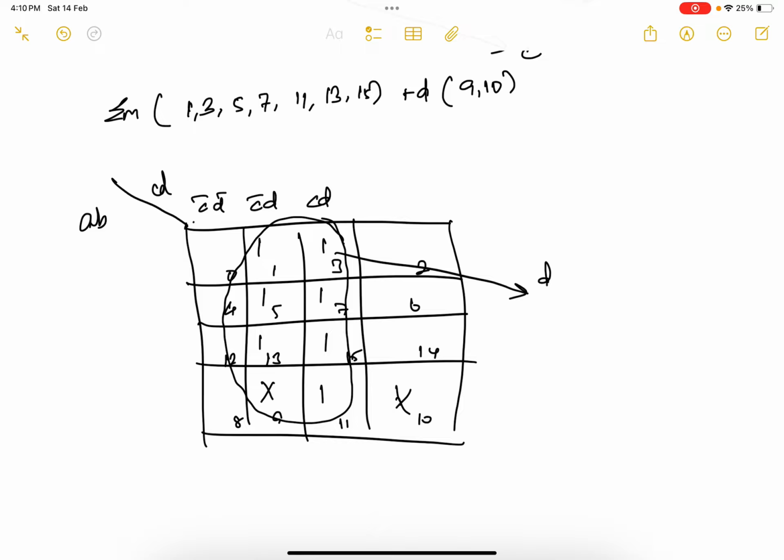But in this case, if I added one more 14, what will you get? You will get a structure like this. So here if you see, I can form 14 and 10 as a pair, but there is a possibility of making 15, 14, 11 and 10 also as a quad. Okay, one can also be left and made a single, but a single is not permitted. You want to go for the maximum possibility. So making a pair is possible, but when compared to the pair, making a quad is also acceptable.